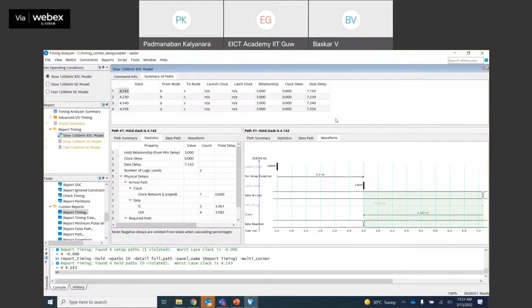During our hands-on lab, we will have a case where there are 2 clocks, more than 1 clock in the design, and we are going to understand how to constrain them. In that case, it will be very interesting for you, where we try to impact one and it provides a negative impact on the other. So those kinds of considerations should also be taken into account.